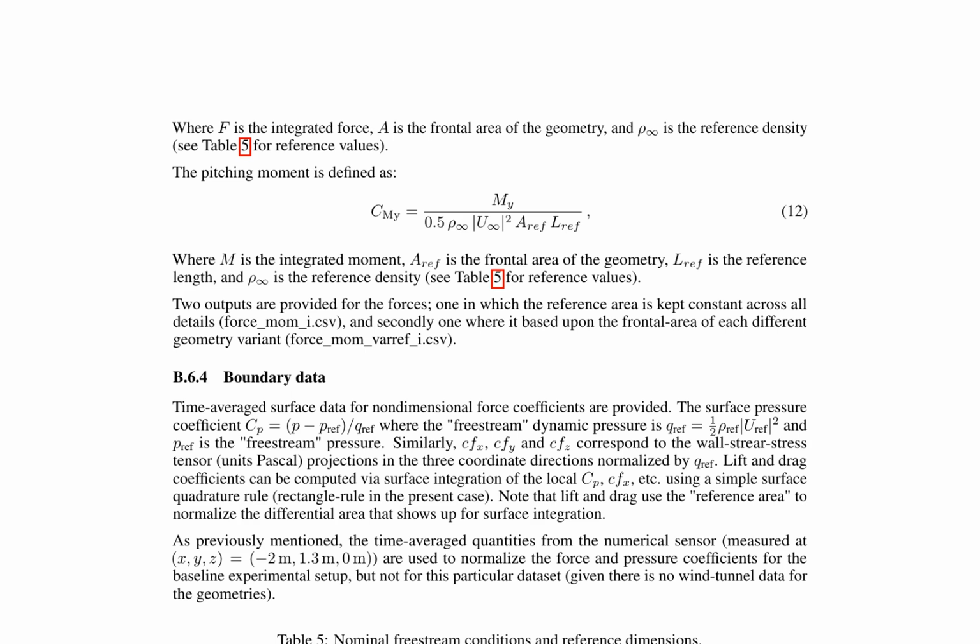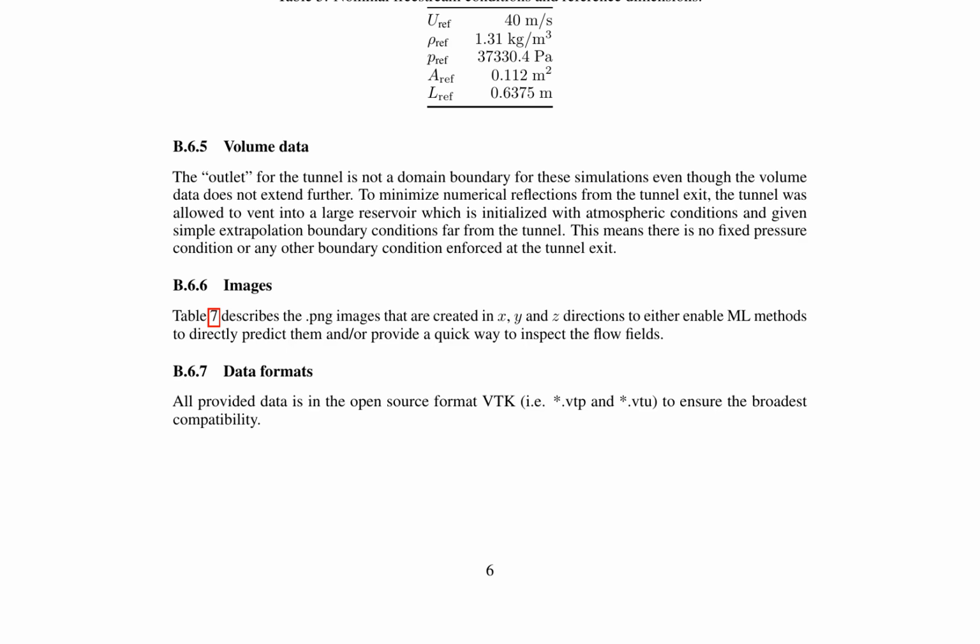The boundary data section explains that time-averaged surface data for non-dimensional force coefficients are provided, including surface pressure coefficient Cp, wall stress tensor projections Cfx, Cfy, and Cfz. These quantities can be used to compute lift and drag coefficients via surface integration.